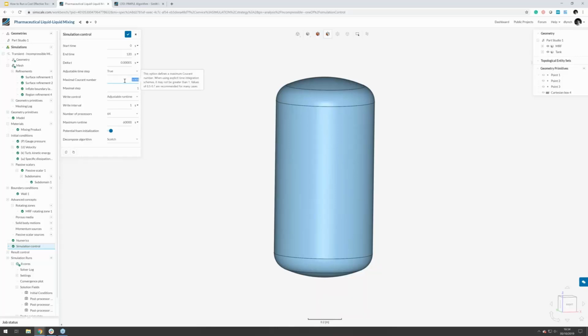And that's what this parameter means. It says, are you able to change your time step to make it more cost effective? Because if you were to do the same time step over and over again at a very, very small time step, then that would end up racking up a lot of core hours and a lot of expense to you. What you want to do is minimize this and push it as far as you can without going above a reasonable limit.